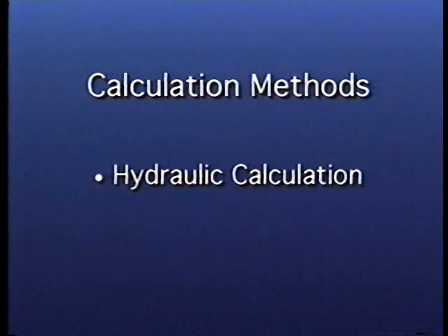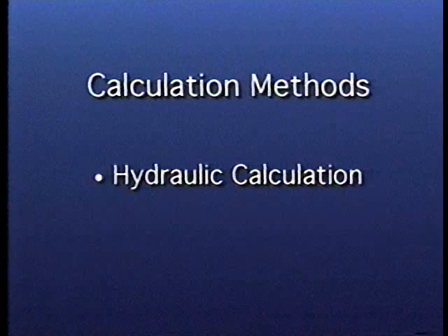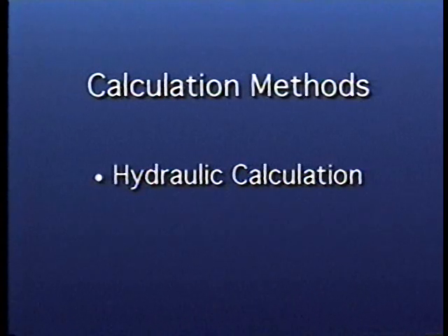The hydraulic calculation method establishes the water supply based on the expected area of the sprinkler system flowing at a minimum rate. This information is contained in curves showing the flow rate per unit area, referred to as density, versus the area of the sprinkler operation. The curves are determined from fire tests, fire experience, and professional judgment.